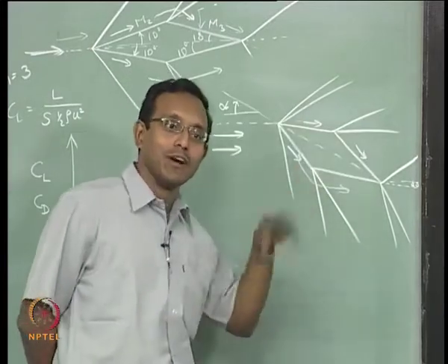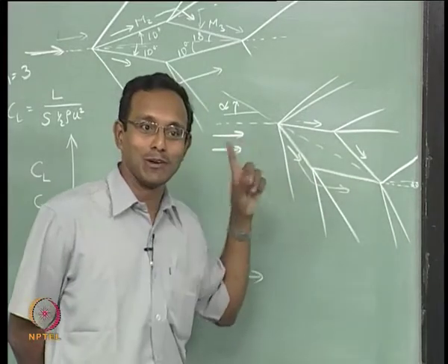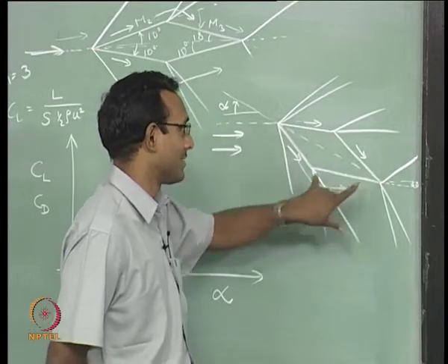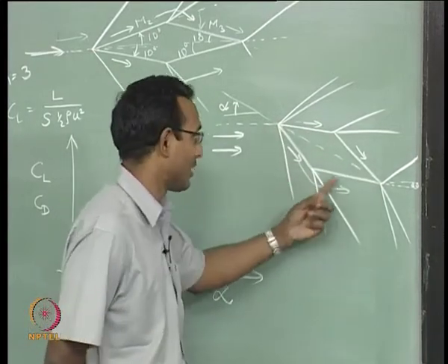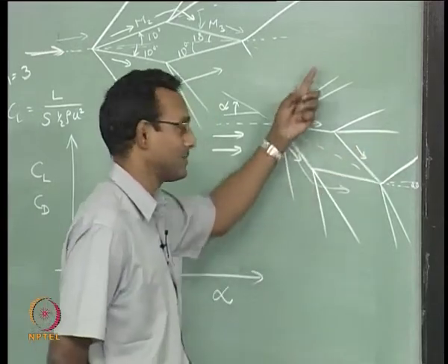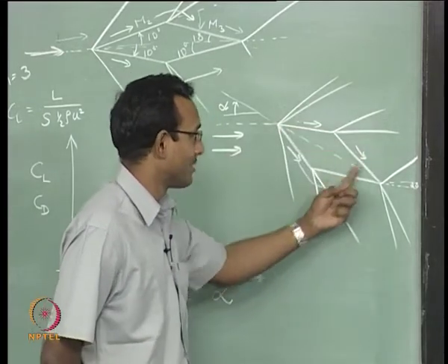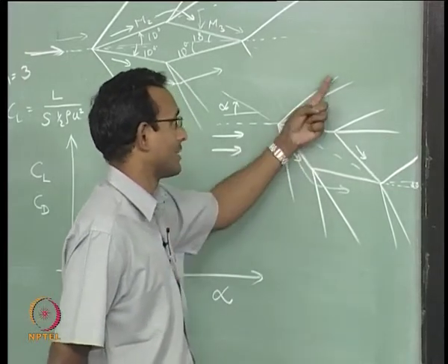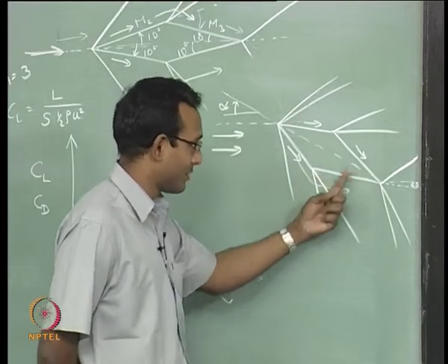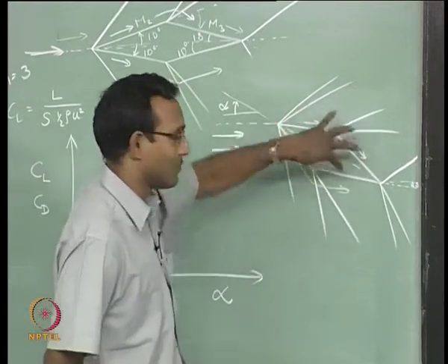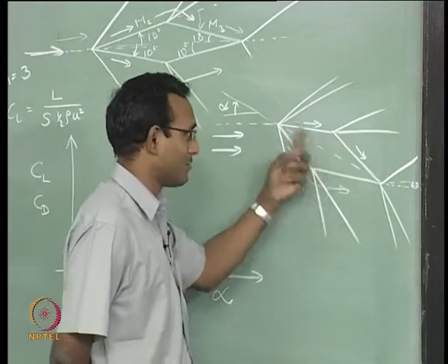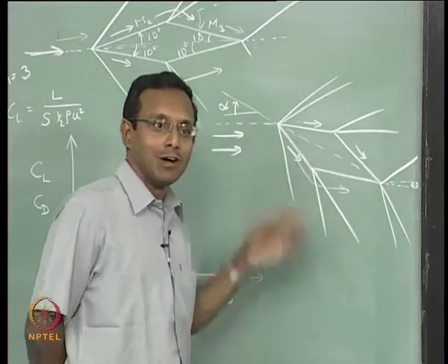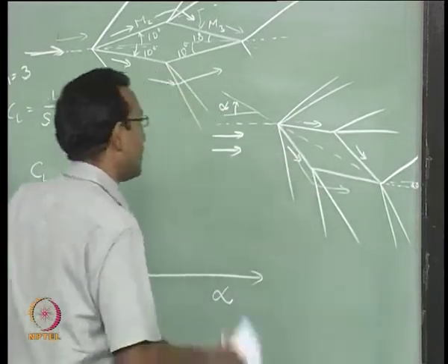Okay. But you can go and prove it if you go and solve this problem for one particular angle of attack. You can prove that the pressure here is higher than the pressure here is higher than the pressure here, all that you can just prove it. Actually this will also have force like this, will be lesser force compared to this, so it will start rotating like this. If I consider this surface and this surface, that will be a net force like this. This surface and that surface, net force will be like this, but a smaller quantity. Overall there will be a moment, and this net force will be the sum of these two forces, that will be like this. This component is the lift, this component is the drag. All that is sitting inside that. Okay. You can solve this problem.